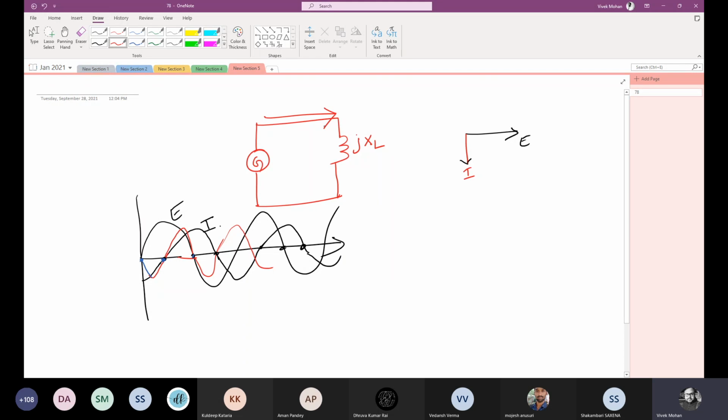The negative waves represent instantaneous power delivered by the load to the source. The duration of each wave corresponds to 1/4 of a cycle, pi by 2, of the line frequency. So the frequency of the power wave is again twice the line frequency.